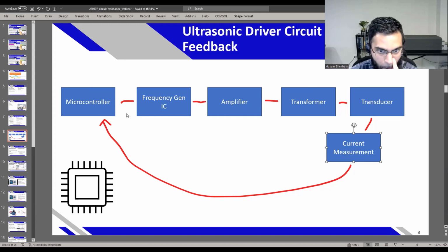Let me know, I actually don't know. I assume at this frequency it's going to be tricky. So why not go with something more stable and dedicated? You can buy an RMS measurement IC, or you can use more basic peak detect circuits, which I'm going to show.